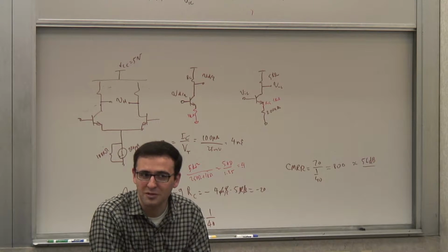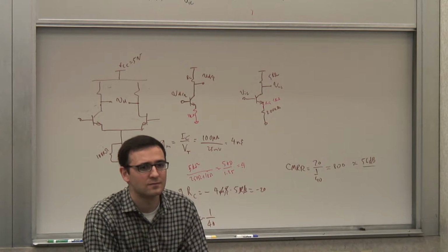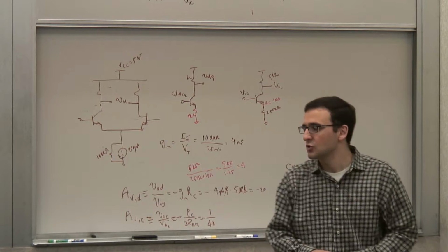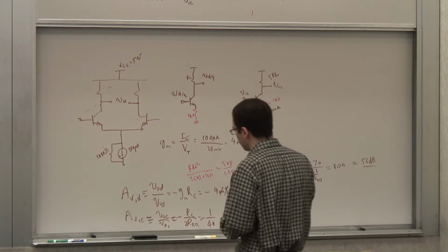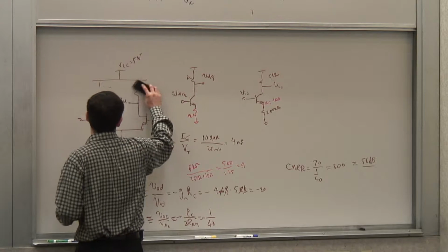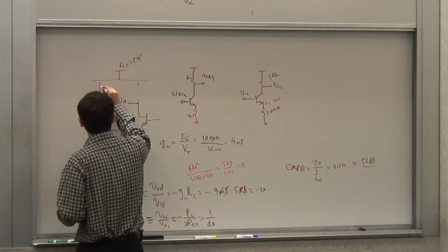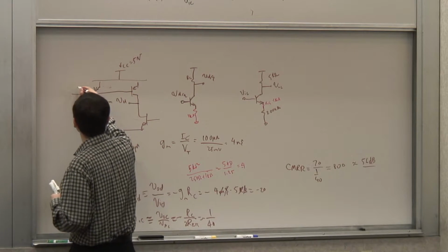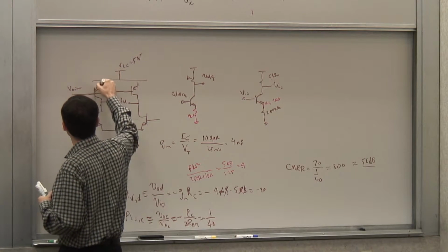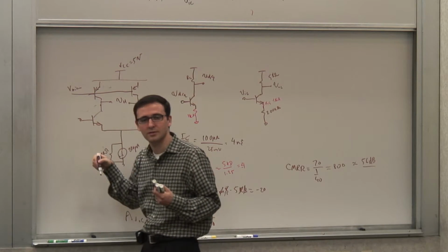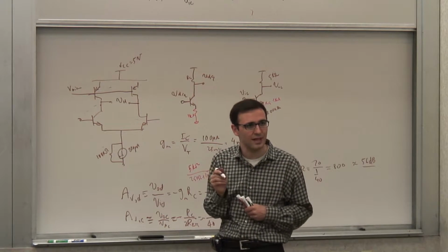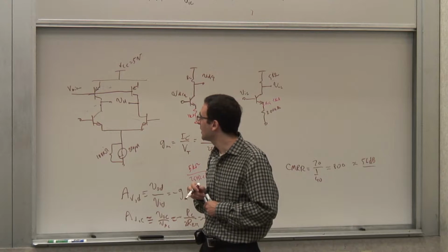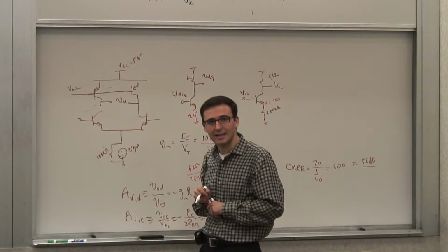We have had a similar situation before. Yeah, it's a current source up there, an active load, right? So if I use a transistor, let's say a pair of PNPs this time, if I put a PNP transistor here and a PNP transistor there, and keep them biased at a constant current, let's say 100 microamp in each branch, initially the balanced case, what happens is that now I can get a much higher gain.